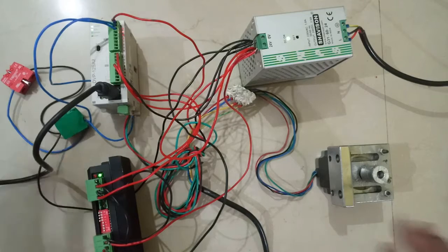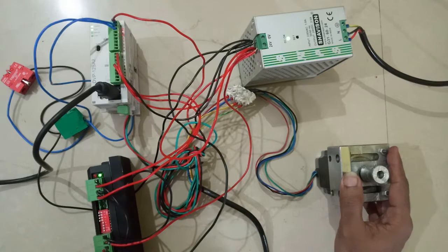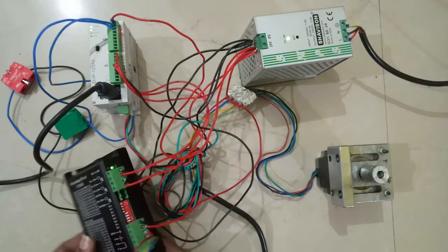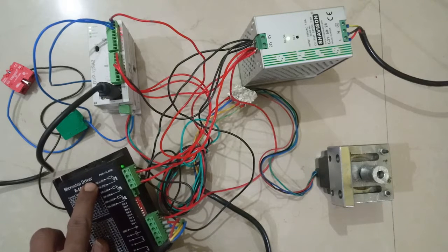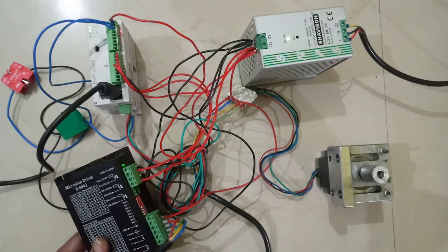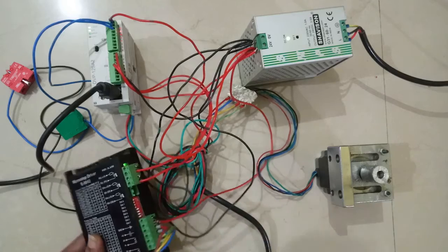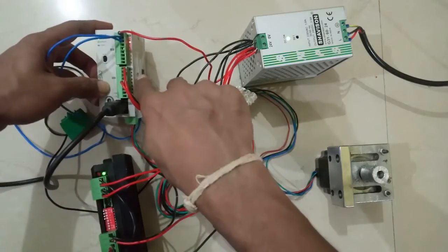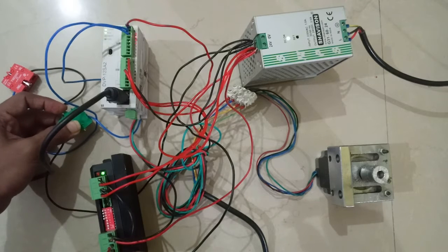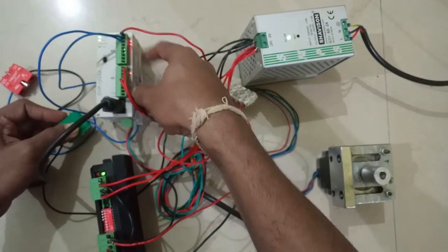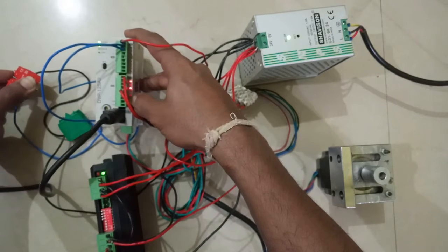counterclockwise. So here, there are 2 systems to drive a stepper motor or any motor, that is clockwise and counterclockwise, and pulse and direction. Here you can see there is pulse and direction. So in this system only one input needs to be pulsating, that is a continuous train of pulses, and the other one is just, sorry, you can say high or low. So in this case the Y0 bit is a pulsating bit and Y1 is high or low. So when I press the NO contact, you can see only Y0 is on. Okay, and when I press this switch, both the LEDs, that is Y0 and Y1, are off.